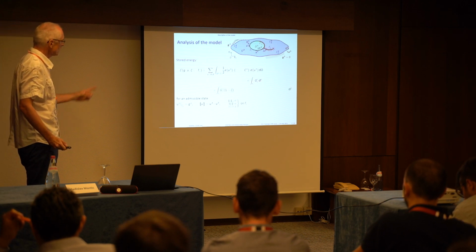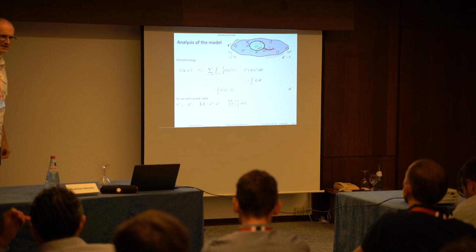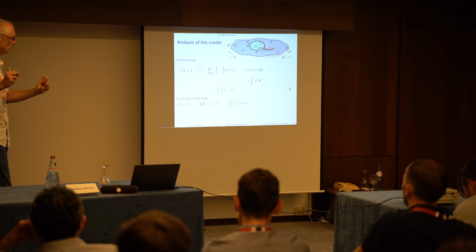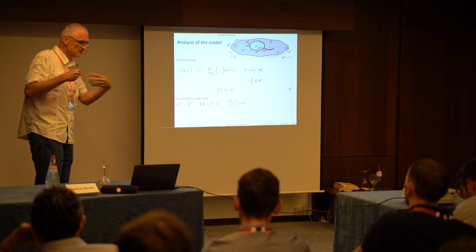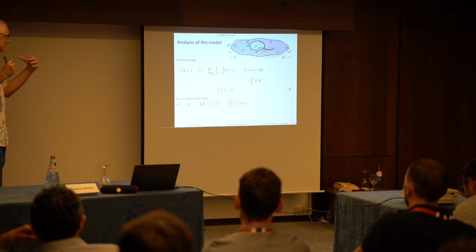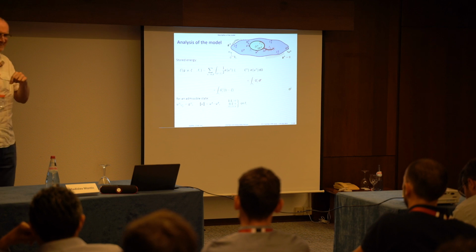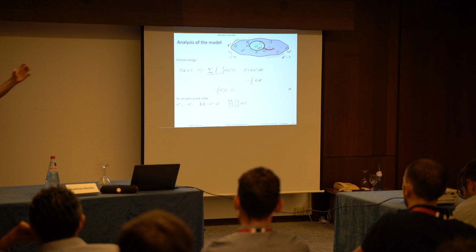write this integral using the internal parameter zeta. Well, it is a damage-like parameter which varies between 0 and 1, but originally it was considered as a parameter of adhesiveness. Value 1 pertains to the intact state and value 0 to the full damage of the crack. So it may be a bit confusing for those who work with damage parameters. Nevertheless, just imagine that 1 minus zeta is alpha, etc.